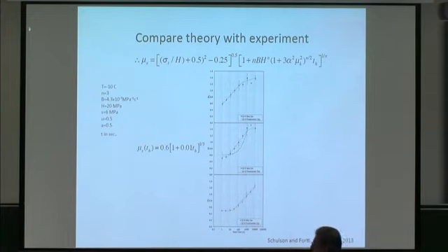Well, a variety of materials parameters are in that relationship, and one can see the power law creep relationship in terms of stress to the power n. We chose n equaling 3. Perhaps not a very good number, because as Barnes, Tabor, and Walker taught us so many years ago, the n value increases with stress, particularly at stresses beyond an MPa.